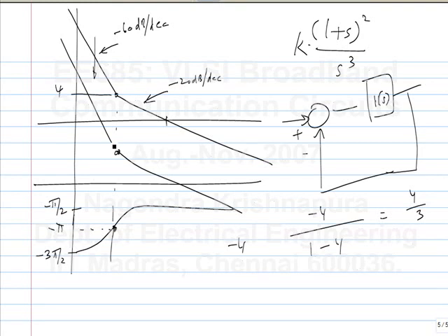As you increase the value of the gain, this is what you do in root locus. You have some gain factor, you keep on increasing it and plot the loci of the roots. The roots can go into the right half plane, then for higher values of gain, come back into the left half plane. You might have seen root loci like this. So if your system is operating somewhere here, you can have frequencies where the phase shift is pi and the gain is more than 1, but it is a stable system.